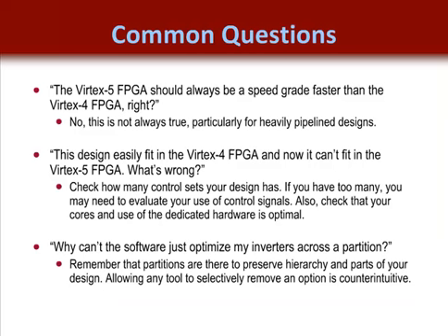Well, this whole idea about partitions is for the designer to control the hierarchy and preserve logic. So if any tool just went around and changed logic, added the inverter and recoded it, customers would scream because their logic would change, and of course then the simulation, the verification results would have to be gone through again. So it would be counterproductive to the whole idea of true incremental design and maintaining partitions.